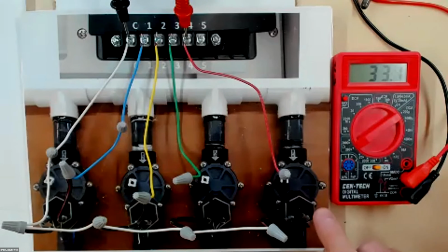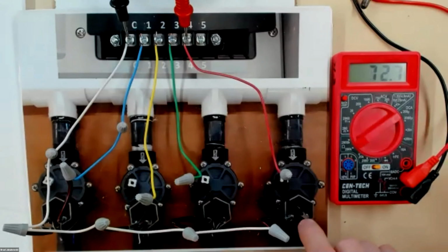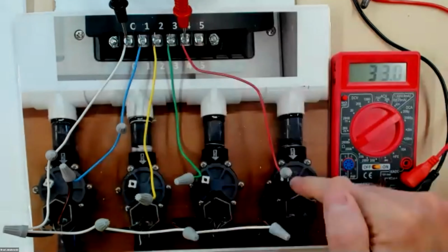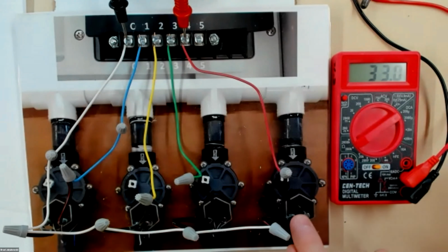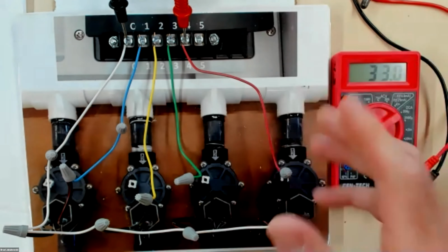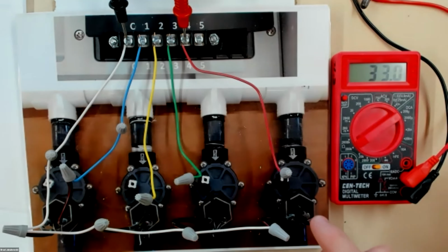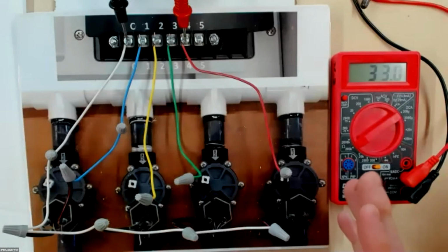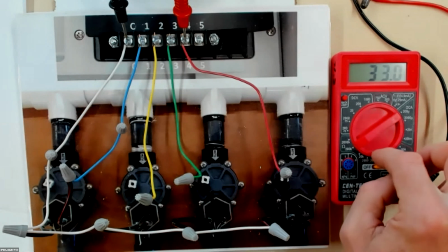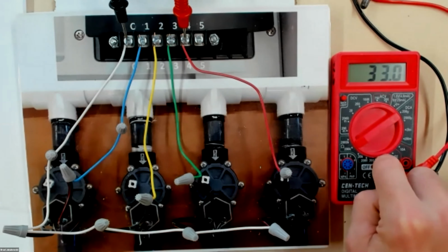So if you installed a 33,000 ohm resistor in here, you could also install, let's say, a 600 ohm resistor in there, which instead of indicating an open or a different kind of solenoid, could maybe tell you that it's a partial short, that maybe there's a bad connection somewhere and that wire is touching the ground outside, or it got wet. And so the waterproof circuit is no longer very good, and it's giving you kind of a partial funky reading. And so this is one way to force them to think about that. It's like, oh, just because it's an open doesn't necessarily mean it's a complete open.